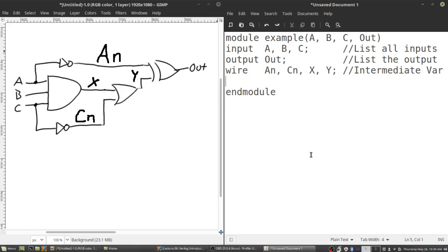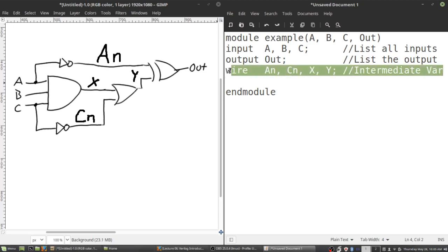So we already looked at doing this example in structural notation, but now I want to look at doing it in Dataflow and see if it looks any easier. So I kept all the same wire names here, but as it turns out, in Dataflow we don't necessarily need as many wires because we can encapsulate multiple internal operations in one assign statement. So actually what I'm going to do is go ahead and remove this line. We don't really need it for our data flow expression.